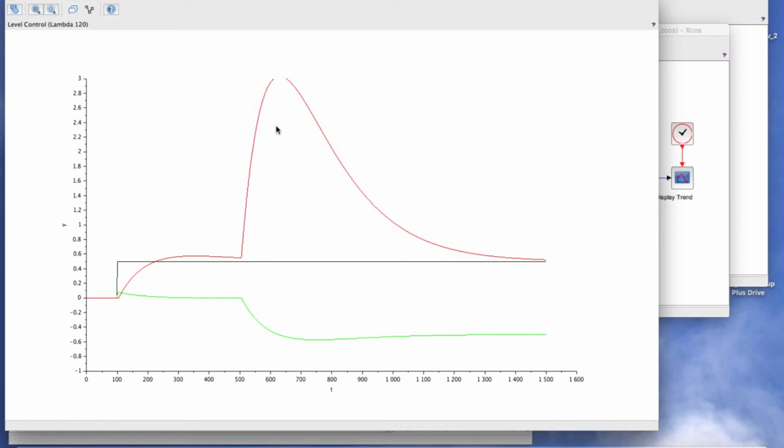For the load disturbance, the rising level is caught in the specified time of 120 seconds, and the level is gradually brought back to set point over 600 seconds. The controller is utilizing the available hold-up time in the vessel, and there are no oscillations in the controller output.